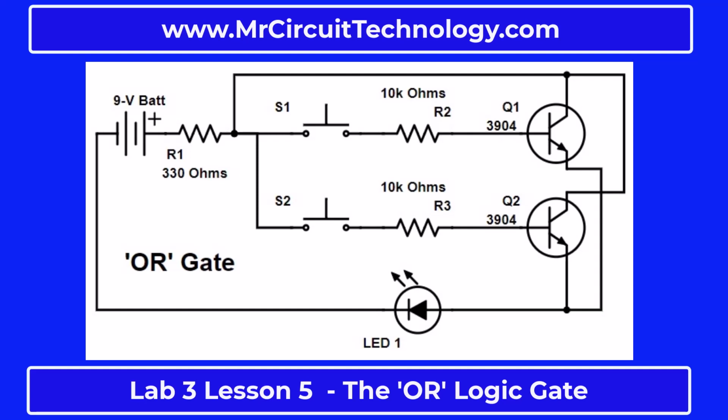You will notice that this circuit has 2 transistors, 1 LED, 3 resistors, a 9-volt battery, and 2 normally open push-button switches. As in all digital logic gate circuits, when the LED is lit up, it means that there's a true on the output.